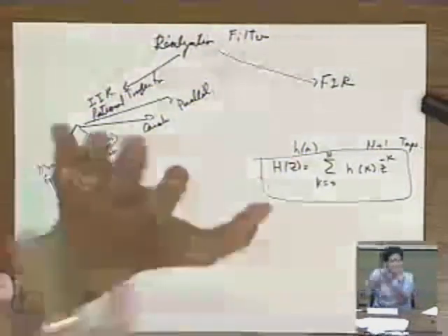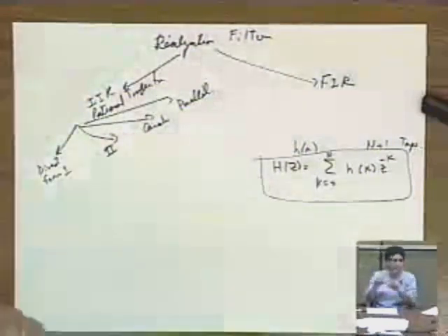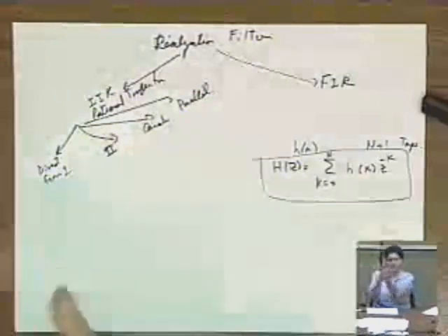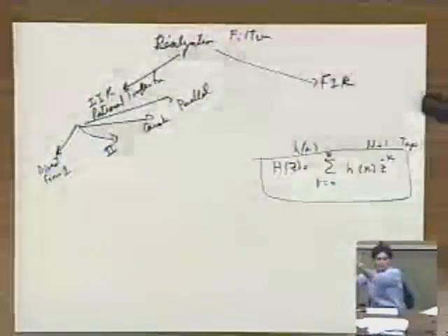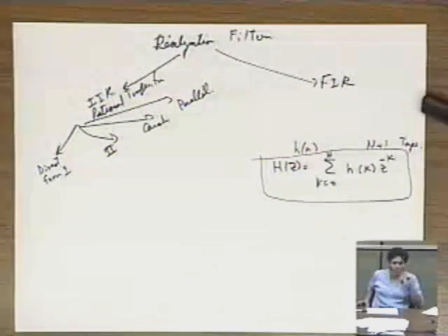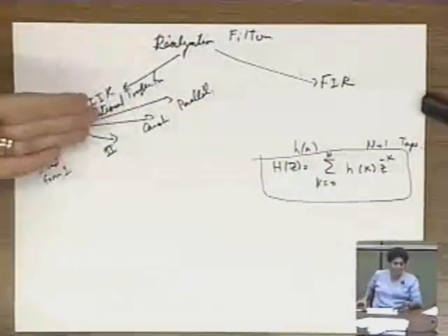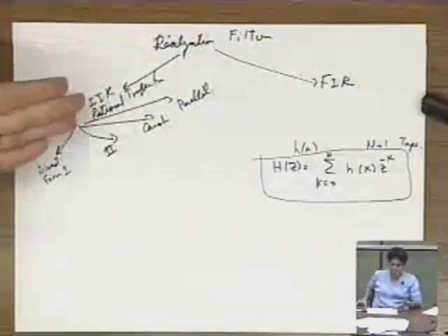Good old convolution. You've got 5 taps or N taps, and even if you have a stream of infinite length of sequence of numbers coming in, you just flip the 5 numbers that are your FIR filter taps, multiply, add, shift, multiply, add, shift, multiply, add, shift, and the output just keeps spitting out. For IIR filters, you couldn't do good old convolution because there were infinitely many taps in it. And so the difference equation was a way that rescued you from that situation, specifically only if they had a rational transfer function where you could have a difference equation.